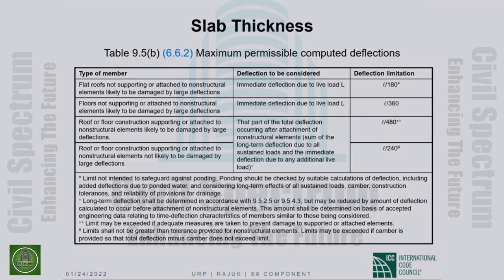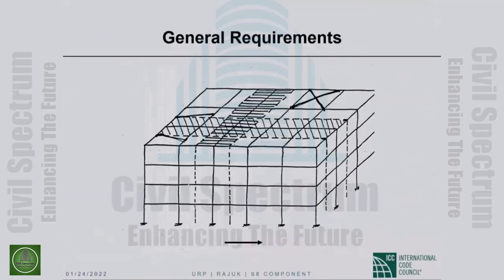Anyway, I would suggest that you do not get involved in calculating deflections of two-way slabs and trying to show that they're within limits. You are much better off not making them particularly thin, because that will bring you problems down the road.